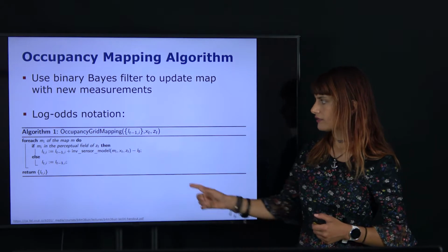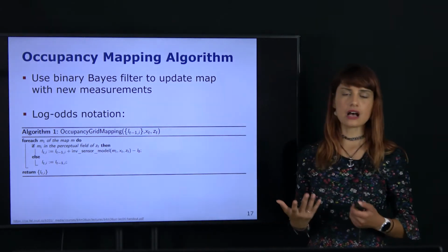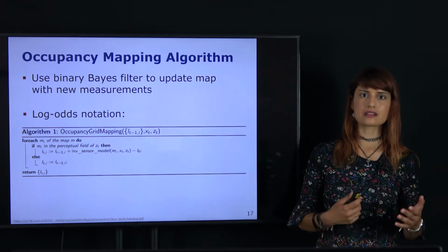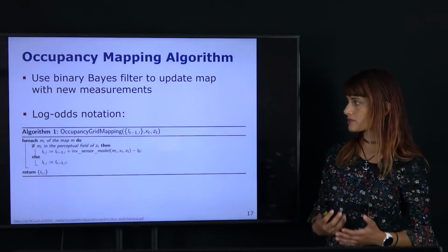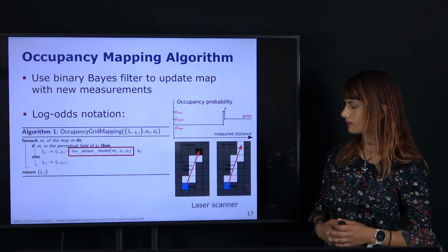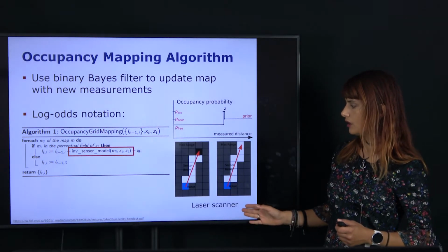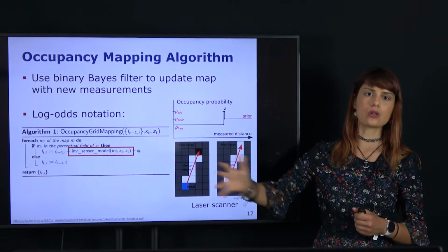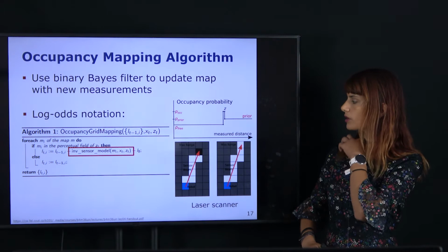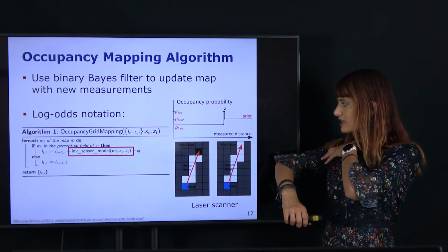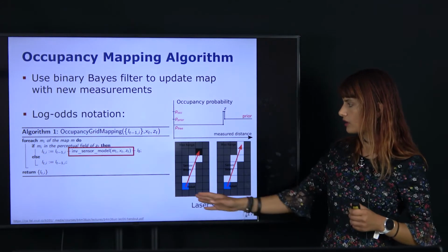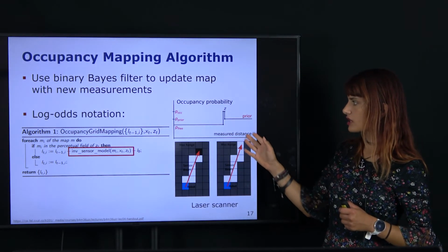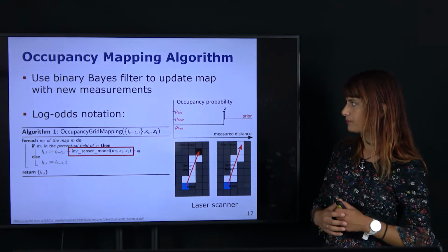Now, how do we define the sensor model? This highly depends on the physical world and the properties the sensor exhibits there in terms of its behavior. So if we have a laser scanner, we essentially shoot beams and figure out the perceived depth along that beam, registered by the robot. So for the sensor beam, we have such a distance-dependent variation of occupancy probability.